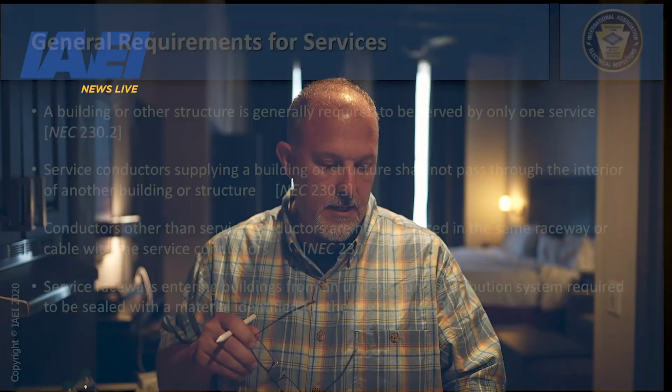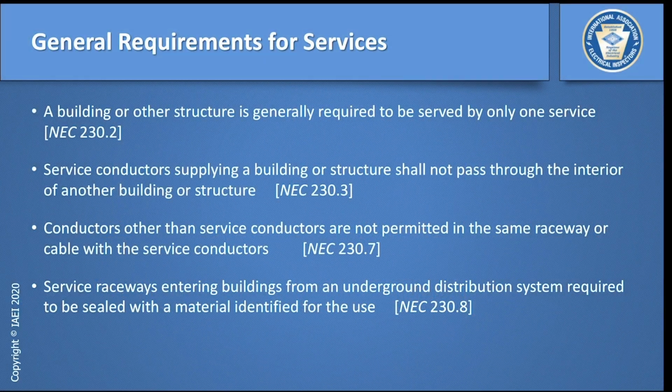And what 230.7 is telling us is that conductors other than service conductors are not permitted in that cable or the raceway. So if I have a raceway, a conduit, etc., and it has service entrance conductors, we treat service entrance conductors very special.